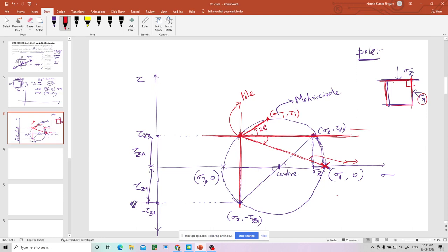You can draw a 26 degree line here. So this is the plane in this element which is subjected to this much normal stress and this much shear stress, sigma I and tau I. That is the concept of pole. From the pole, wherever you draw, just reproduce the same lines with the same angles in this element, and you will get the angle of the plane. You can represent the plane in this element.